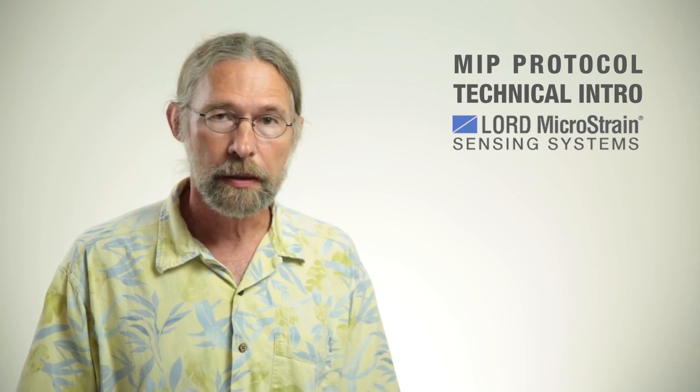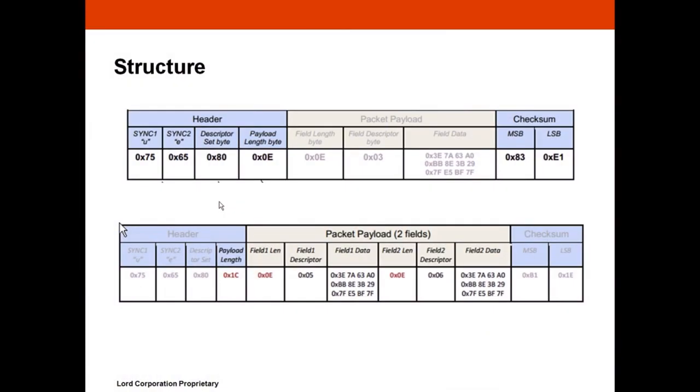The next byte in the header is the descriptor set byte. This is one of the key features of this packet. It describes what type of data is going to be in the packet. And then a familiar payload length byte. That's the 4th byte in the header of the packet. It's followed by the packet payload, and at the end is the Fletcher checksum. It's a very common packet structure.